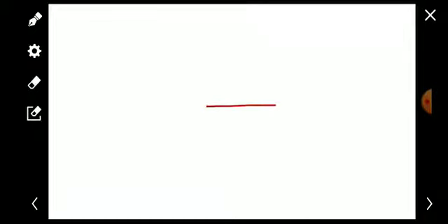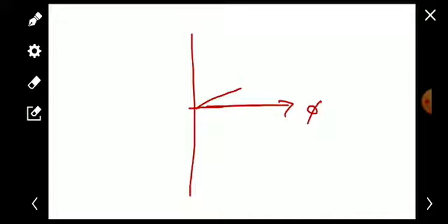That is flux, the flux phi is here, and we are drawing a small current, the no-load current I0, here. This is I0. And we know that the induced EMF E1 is 90 degrees lagging with the flux phi, as we have already learned.